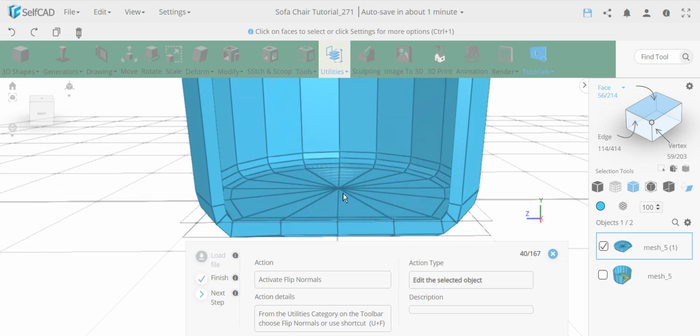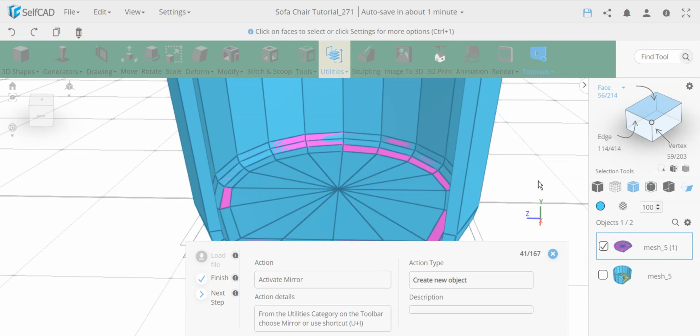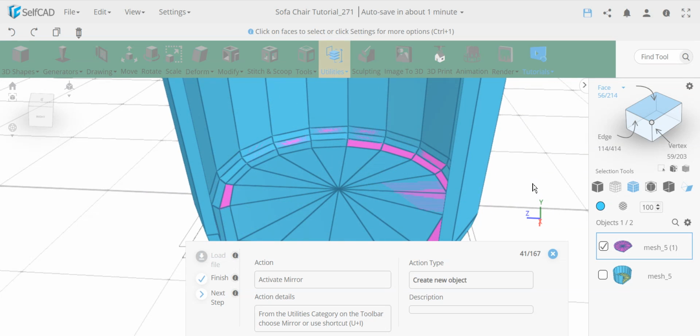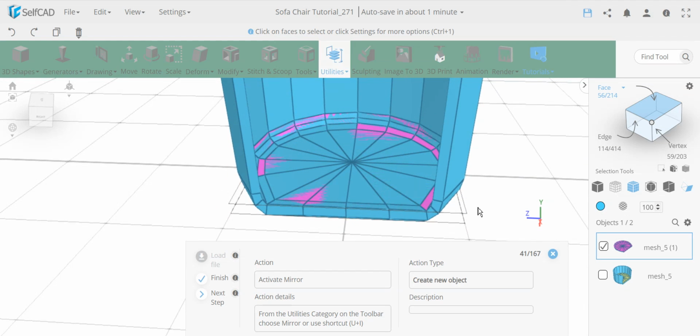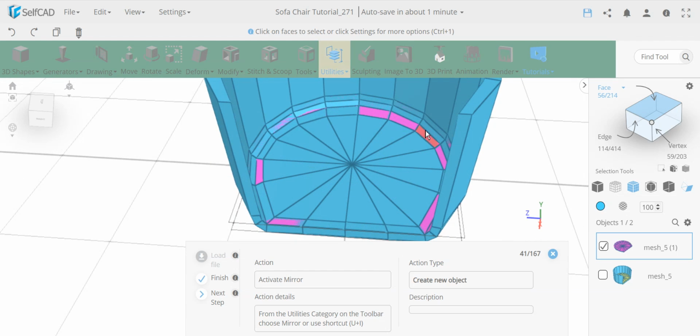However, what we're going to do now actually requires flipping this. Let me show you. So we're going to flip normals. And once we flip it, now we have the Z-fighting thing because they're in the same position. You can partially see the inside color, partially not. Depending on the camera, you see more of one color or the other. What we have done here is made a copy which occupies the exact same space as the first one, and we made it point outwards, so it's a flip.